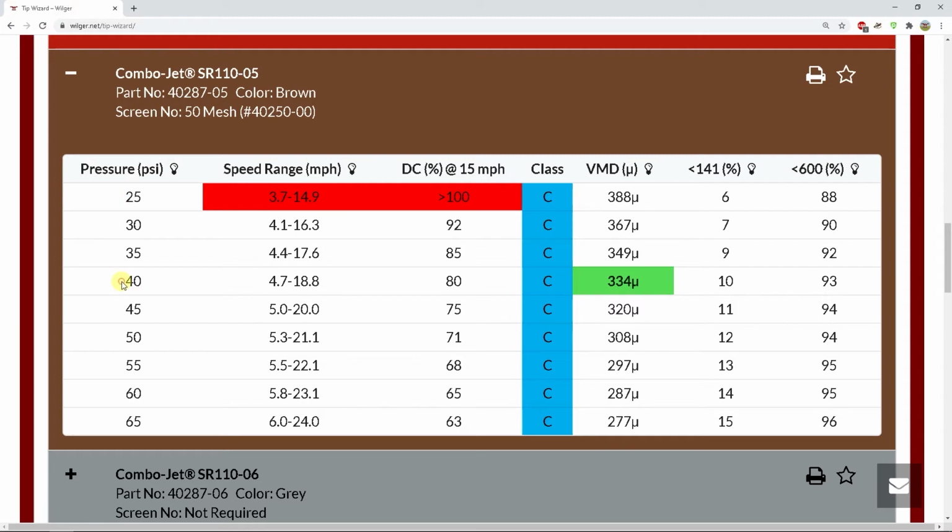So for this example, at 40 psi, our duty cycle and speed range is sufficient. As far as duty cycle side of things, you'd want to try to keep it between that 60 and 80% duty cycle. Again, just so that you have enough flexibility on the speed range, both up and down. But more importantly, if you do have a turn compensation mechanism built into your pulse width sprayer, so again, reminding you that if your center rack is going 15 mile an hour, as soon as you deviate from straight, the outside section that's swinging hard is going a lot faster.